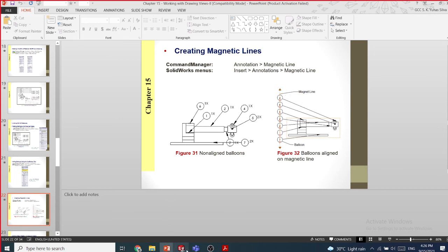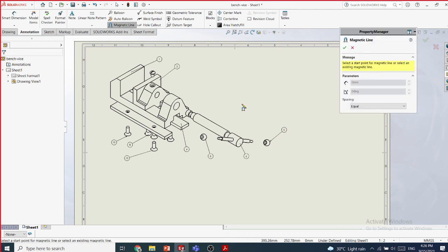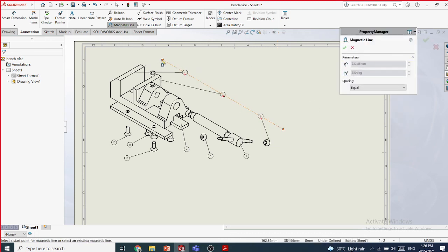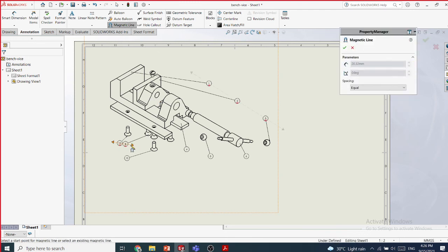Okay, so my work is not good. Here and there the balloons are going all over, so you can use the magnet tool, and it's like the magnetic mates. You just connect these things and put them in a certain line like this, or this way. So all the things have some alignment, not here and there. Okay, so you can apply a magnet to these three and take them separate, and you can apply this and do this.